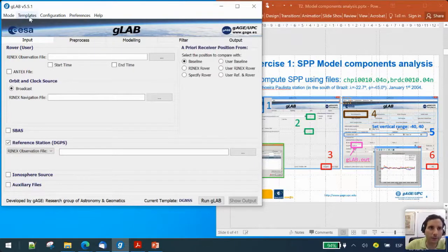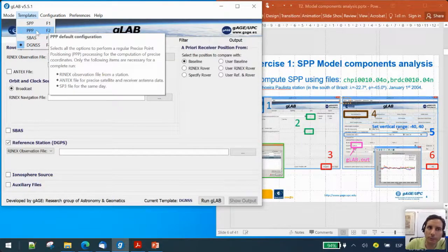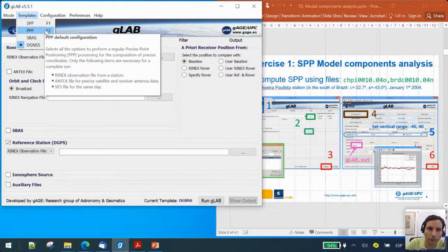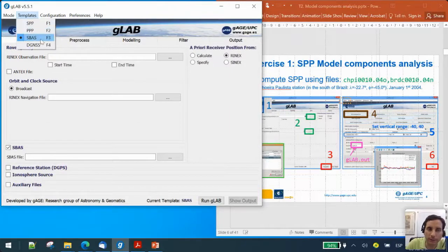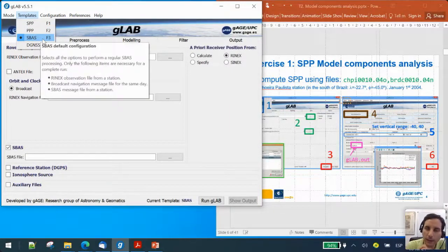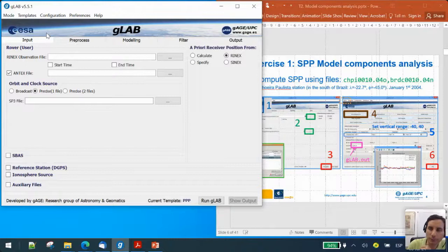Now, after the overview, you know all of these modes, from absolute positioning, SPP, and the differential modes with code, that is the differential GNSS. If we want integrity, then we need to use corrections from an SBAS or a GBAS, and then the PPP, the precise point positioning, that we will be dealing with in detail tomorrow.